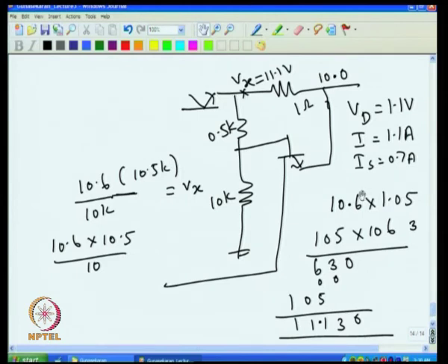So, if you remember it as a reverse bias and follow this example, it will be very clear that fold back current limiting works depending upon the voltage across this. So, one can alter these two resistances to get the required short circuit current. So, this is about short circuit protection given to the voltage regulator.